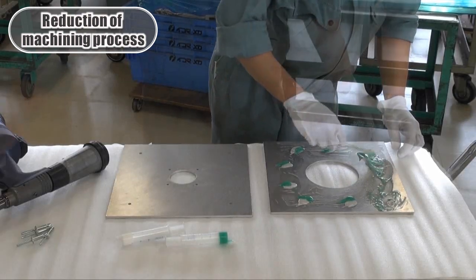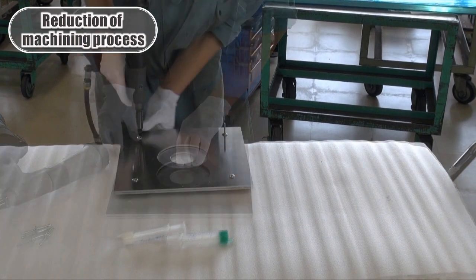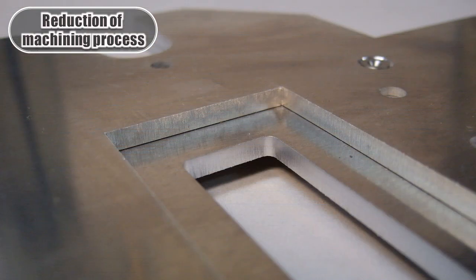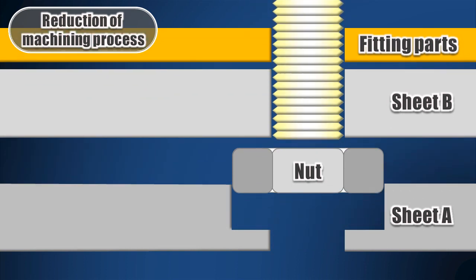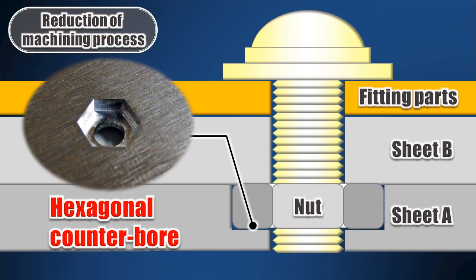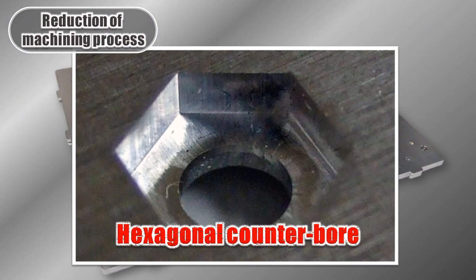Please take a look here. The 2 sheets are laminated, and by making holes and notches in just one sheet, we can make the same shapes with the sheet metal processing. Over here, we use the laminated structure to insert a nut between the 2 sheets to replace the tapping. The hexagon counter bore is made during the blanking process.